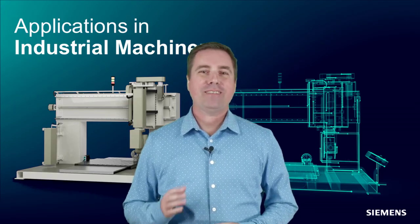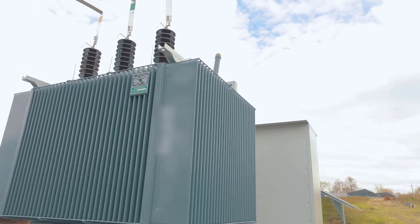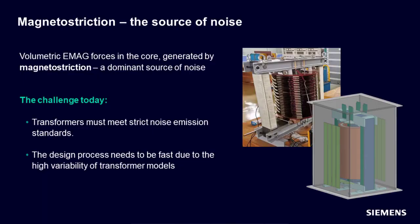Power transformers must meet very strict noise emission standards, mostly focusing on the so-called hum noise. Besides being an annoyance, this noise can give the perception of bad quality of the transformer. For some OEMs to qualify the eMag acoustics models for transformer development, the noise accuracy threshold is relatively high at plus or minus 2 dB from the measured results.